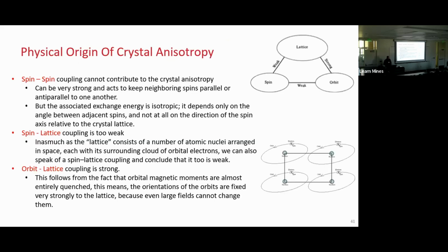All right. So now let's dig a little bit deeper at the atomic level. Where does this anisotropy come from? Where does this coercivity come from? If you think about how electrons spin, previously I showed this picture. There's the electron spin itself, and together it is orbiting around the nuclei. And then you have three other neighbors. Actually, this electron every now and then decides to join this one. So they call it itinerant. So not everyone will bond in here. But nonetheless, let's just see how they are bonding, how they are affecting the anisotropy.